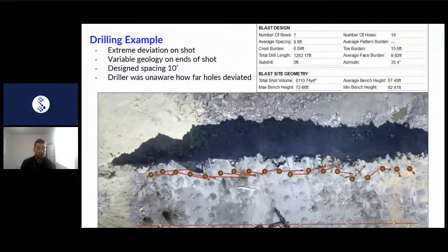After using a borehole probe and measuring this data, we were able to really see where the holes were moving and how that adjusted the burden and spacing between the first and second row holes that we were interested in. Getting this data and then applying it to our loading and timing was also critical, as it's very far from the design shot that we had.